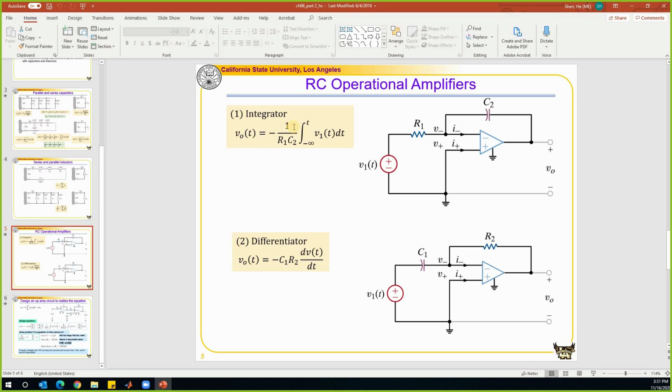So the conclusion that we have for this topic will be more or less the same as what we did for chapter 4, where we first learned operational amplifier circuits. The way to draw the conclusion is exactly the same as what we did before. Do you still remember how we analyze these operational amplifier circuits? So the first step, we state that we are going to use the ideal op-amp model. So we write down the ideal op-amp model conclusions, which is that the nodal voltages at the two terminals are the same. At the same time, the currents going into the two terminals are the same and equal to 0.